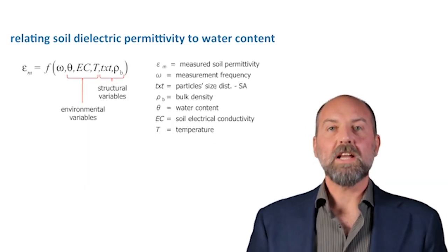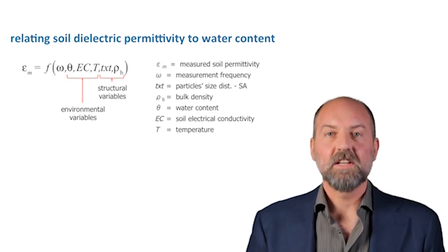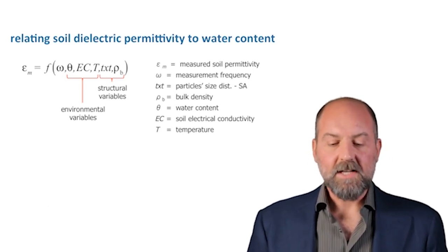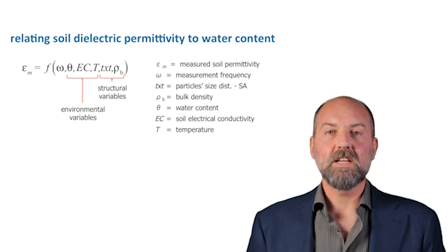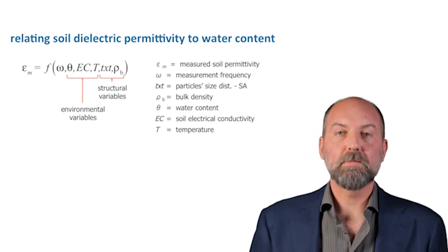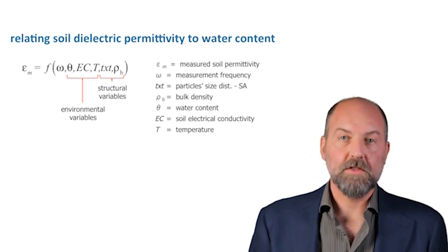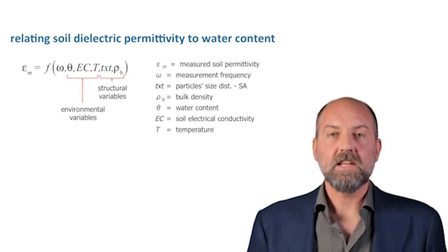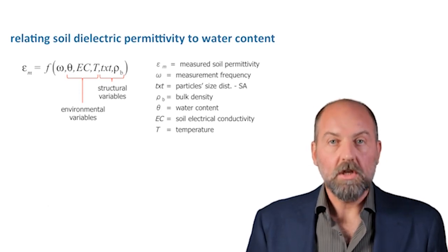So let us formalize the problem by stating that the measured value of permittivity, whether it is obtained through TDR or capacitance, does not depend only on water content.